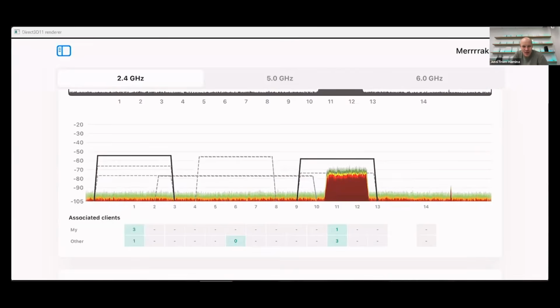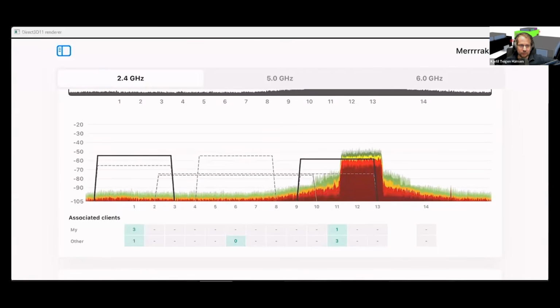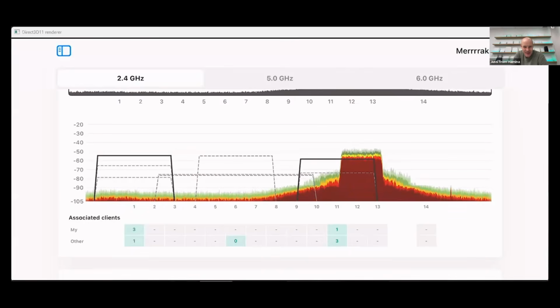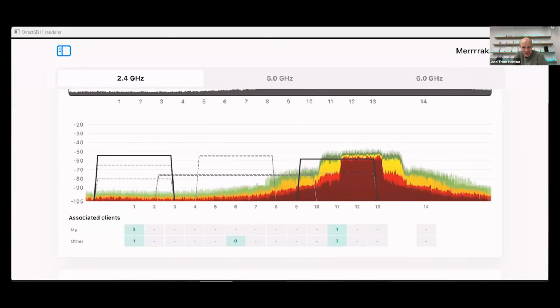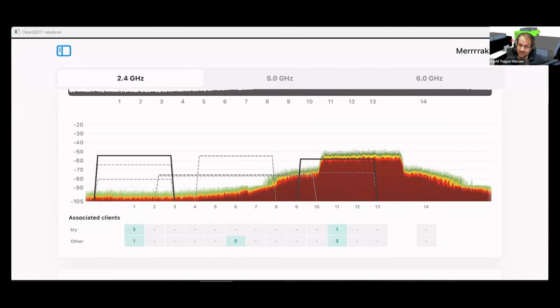What if you raise the amplitude? Can you increase it to above the noise floor or something like that? Yeah, I can do that, but then we usually get a lot of phase noise, because it's so strong. No problem there. But let's see if you can make the beacons disappear from channel 11, for example. Remember, the signal is being generated inside a chamber that has 90 dB of isolation, so it will not escape at all. It's a mobile phone testing chamber.